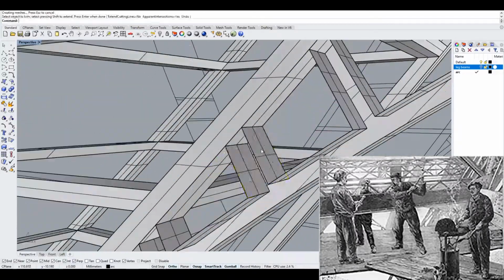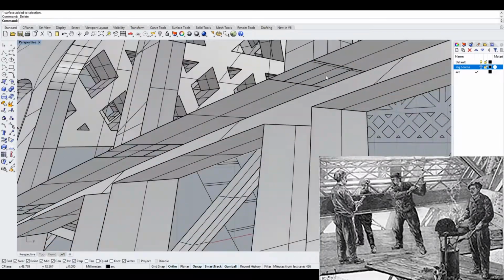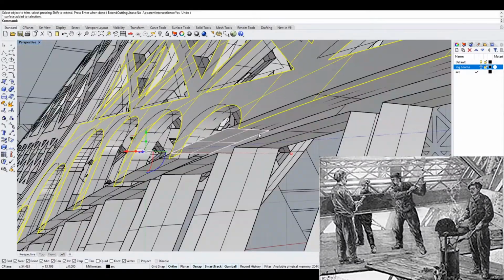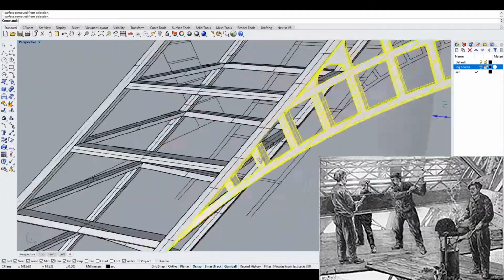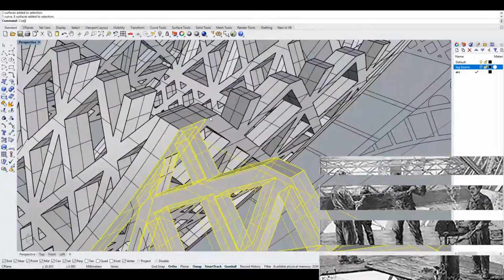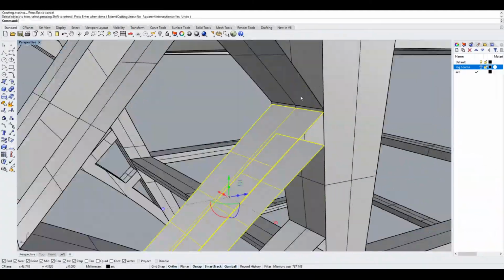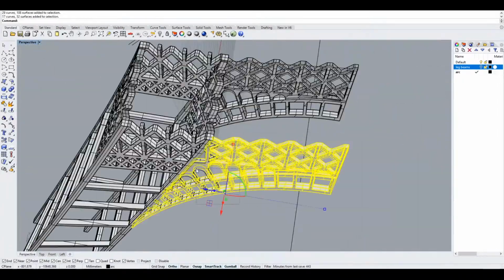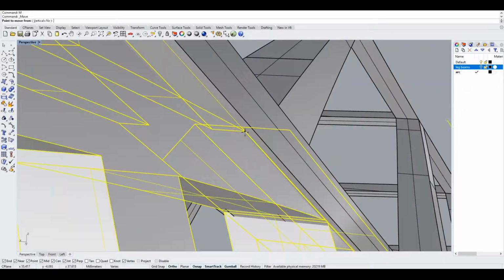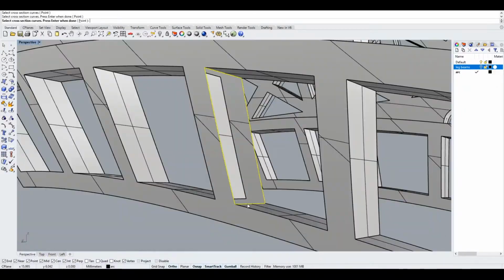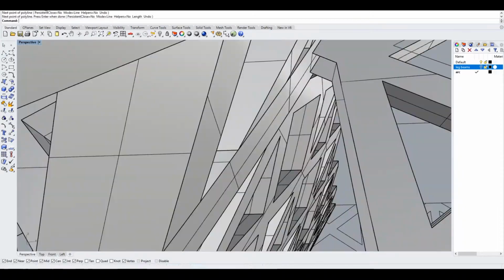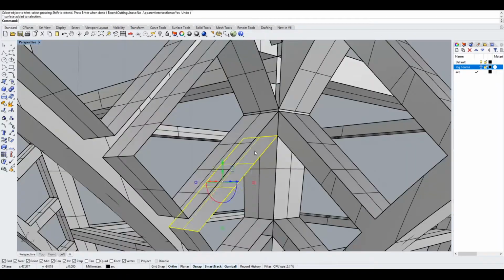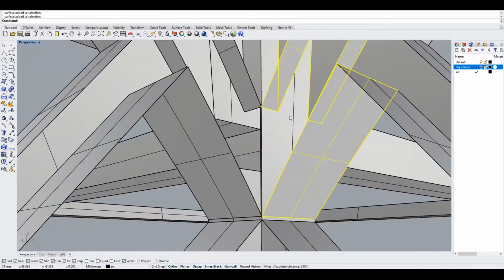A team of 4 men was needed for each rivet assembled, one to heat it up, another to hold it in place, a third to shape the head, and the fourth to beat it with a sledgehammer. The uprights rest on concrete foundations installed a few meters below ground level on top of a layer of compacted gravel. Each corner edge rests on its own supporting block, applying to it a pressure of 3 to 4 kilograms per square centimeter, and each block is joined to the others by walls.